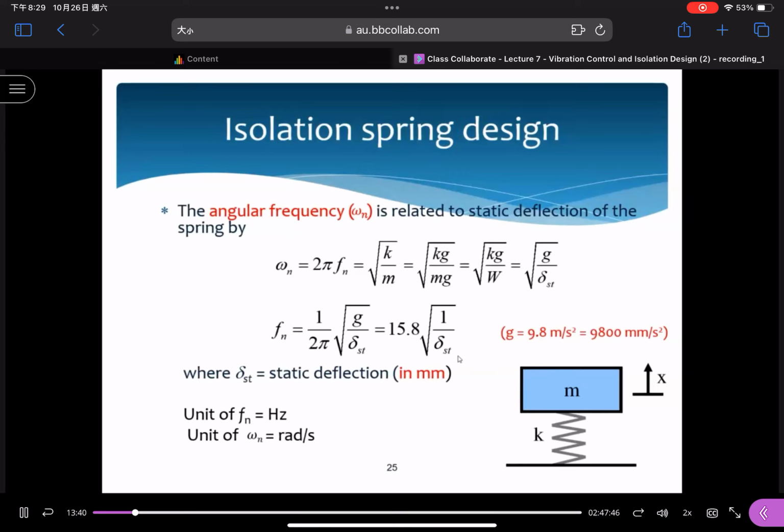You may regard this one as A. A can be calculated by using this equation. It seems so complicated, but don't worry about it. All of these equations could be given. You just need to plug in all the corresponding values into the equations, and you are able to find the overall displacement solution, so you don't need to memorize all these equations for A and phi. You just need to know how to calculate omega n and zeta. Zeta is so simple. It's the comparison between the actual damping value and the critical damping value.